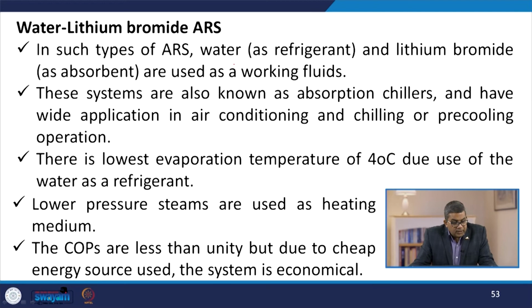Let us talk about the water lithium bromide. Now, in such type of ARS, water is the refrigerant, and lithium bromide is the absorbent, used as a working fluid. Now, these systems are also known as absorption chillers and have wide application in air conditioning and chilling or pre-cooling operation.